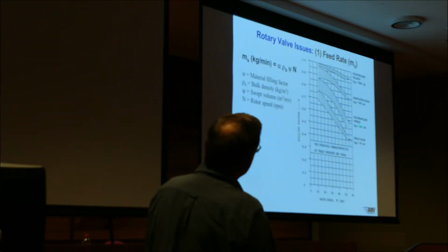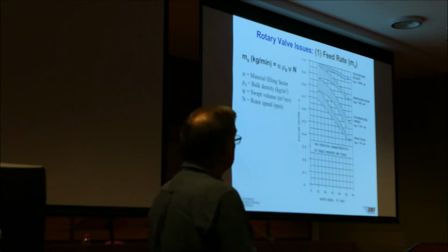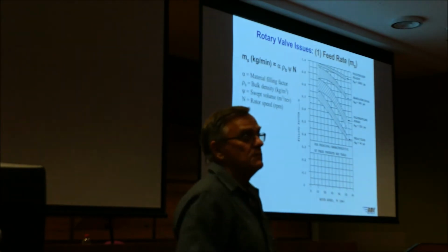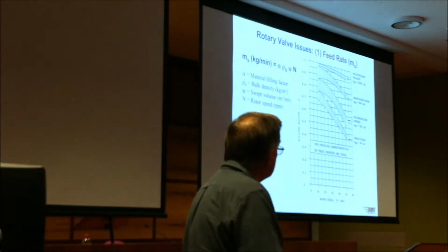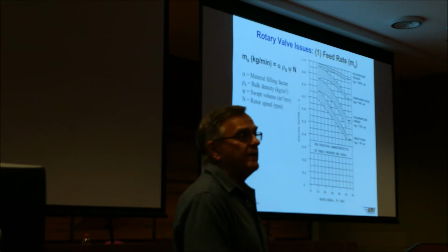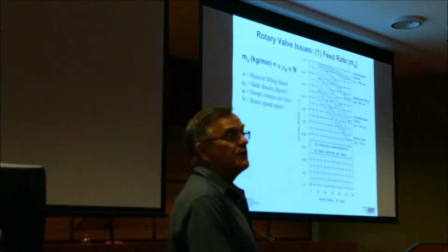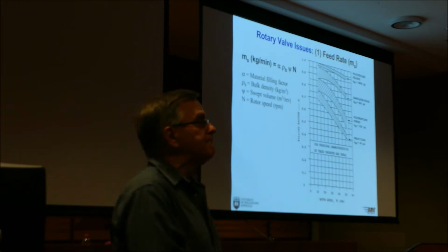And then poly powder, that's just a plastic powder. D50 is 200 micron. And wheat flour that you make bread from is about 40 microns. Now flour varies a lot from mill to mill, so this one's pretty fine. That's a cohesive powder. It's not very free flowing. So here your alpha gets down to almost 0.4. With very high speed valves, it's hard to fill the pockets quickly.